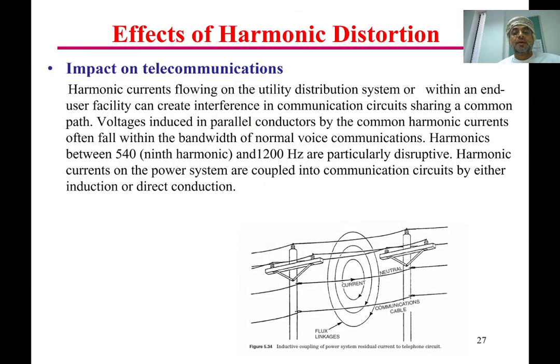Okay, also harmonics will not only affect motors and transformers and, as we said, the energy meter and demand meter, but they can also affect the communication cable which is connected on the same pole, since they can also induce a current in this communication cable, and then it will cause distortion.